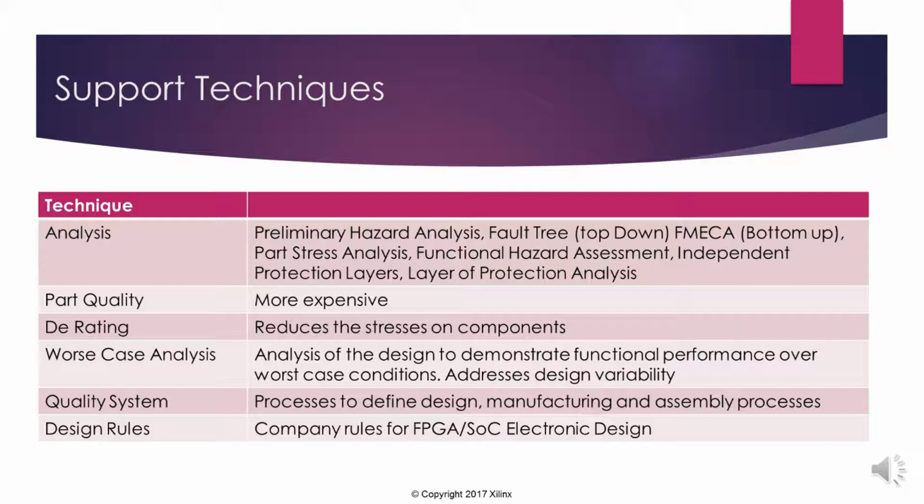Now worst case analysis is where we look at the design and we run through the design for all its worst case possible conditions. So we really try to make sure that this design takes into account all component tolerances, all component drift, all component aging, all component radiation effects if it's going into space, and looks at the worst case conditions of those, and proves that across the entire operating range the circuits can work, and that they will work properly, and that there will be no damage.